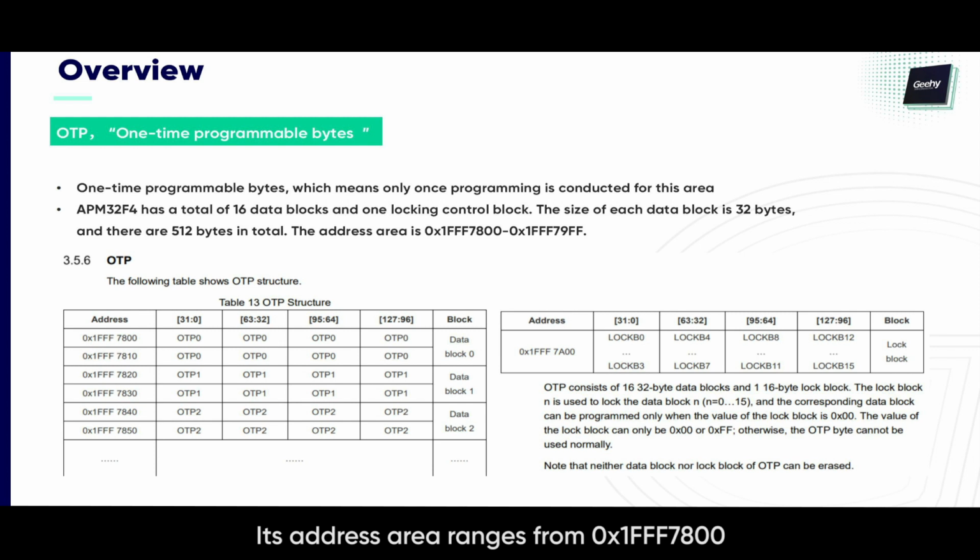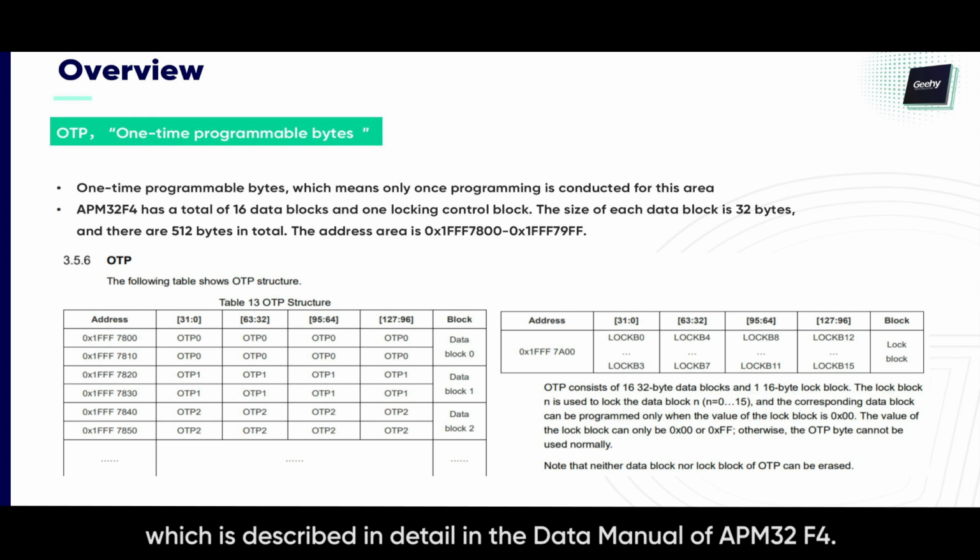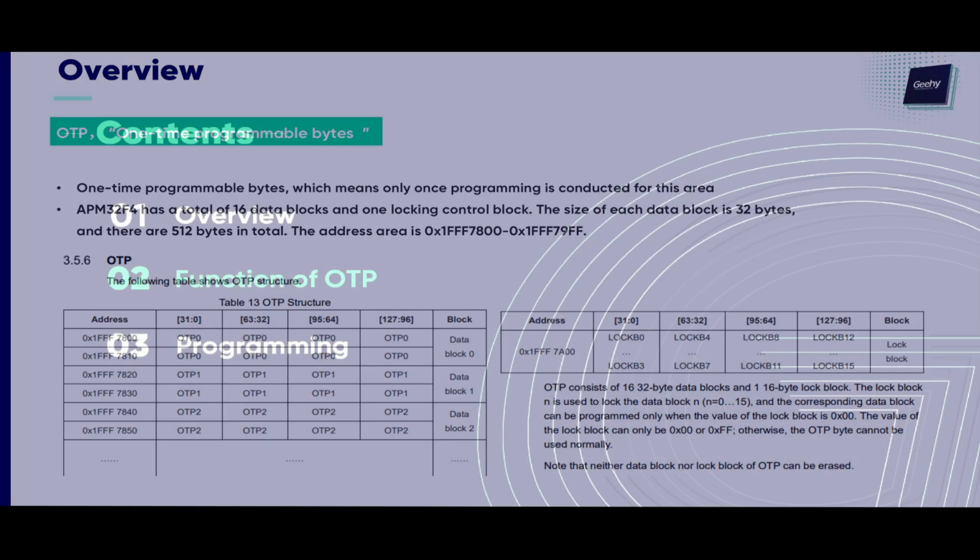Its address area ranges from 0x1FFF7800 to 0x1FFF79FF of our APM32F4, which is described in detail in the data manual of APM32F4. You can refer to the user's manual.